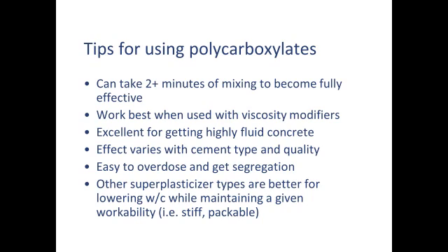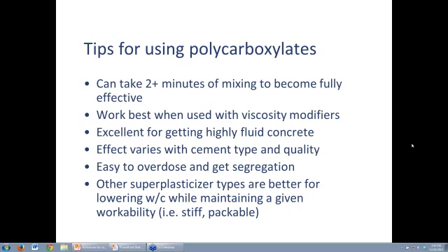They work best with viscosity modifiers, which I'm going to talk about in a second. They are excellent for highly fluid concrete, regardless of the concrete mix design that you're making. They're your best hope of making fluid concrete. However, you have to be careful because it's easy to put too much in and then you get segregation. I'm going to talk about that with the viscosity modifier.